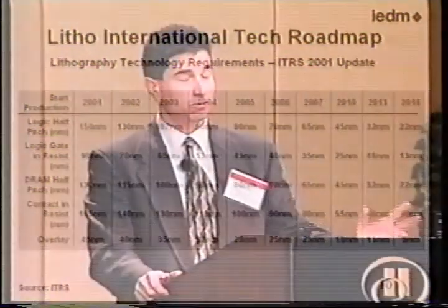Now one of the things that I find fascinating about this particular chart is that our industry tends to put up roadmaps like this without a clue about how we're going to do some of this. So if you looked over, for example, these last couple of columns, and you said, now how are we going to do that? How are we going to do just the line width element of it alone? We really don't know the answer to that. We have some ideas. We have many proposals. We have some theories about how we might achieve some of these smaller and smaller physical geometries, but we aren't absolutely certain. We are still working on that. And that's the same thing, by the way, if we looked at putting in unlanded contacts, for example, or developing these kinds of overlay dimensions from a lithography perspective. We don't have scanners, steppers that can do this kind of capability yet. This is the challenge for the industry. This is what we put up in front of us.